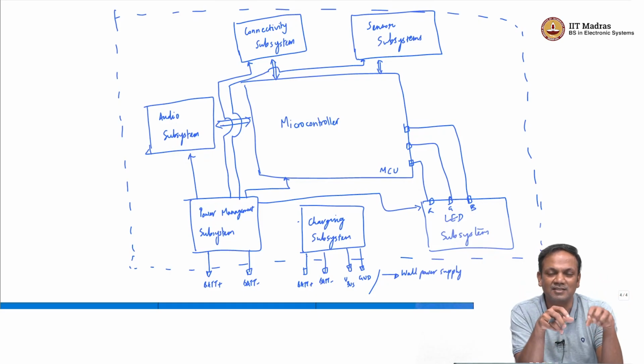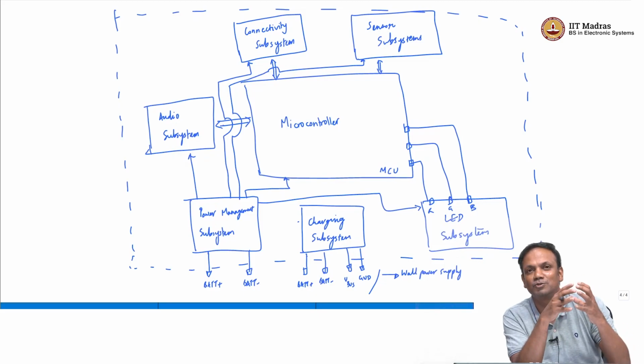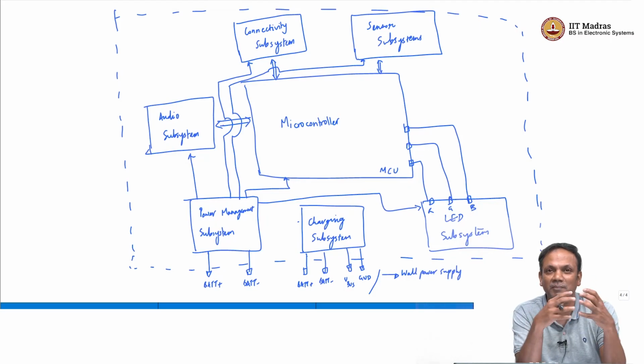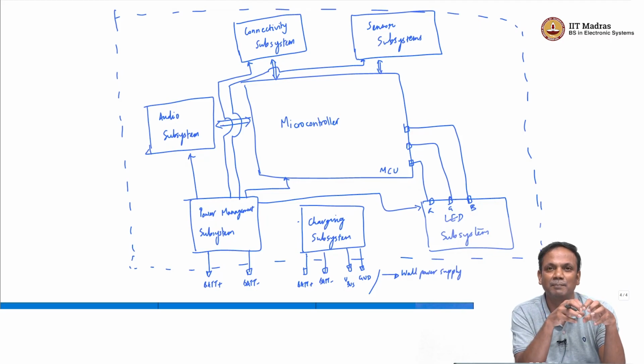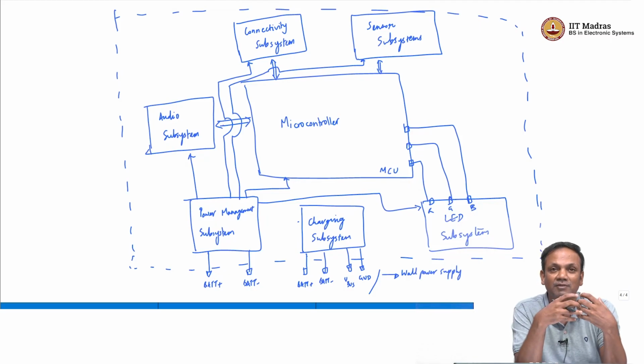The end user has no visibility into that. The end user is trusting the embedded system engineer to make that call for him, saying, okay, this is the experience, maybe I want to do spatial audio. If I want to do spatial audio, this is the amount of resources I need to be able to implement the spatial audio transfer functions. That has an impact on the clock frequency and hence the MIPS, the RAM and the flash, which is the amount of memory that I need of the microcontroller.